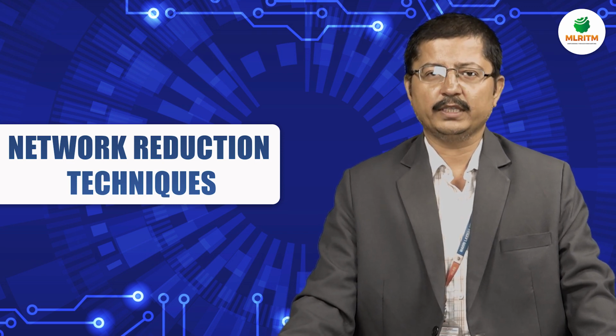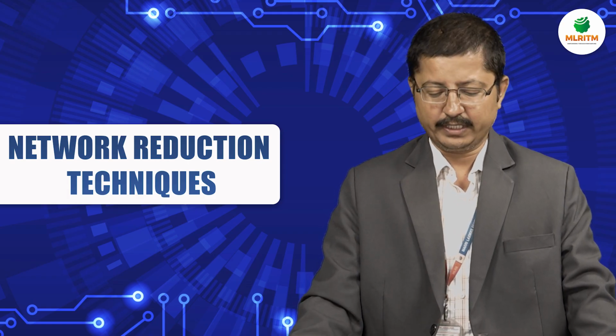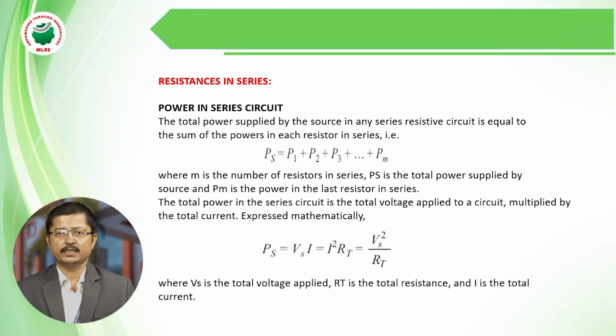To simplify the network, we have to use network reduction techniques. The techniques are series connection, parallel connection, series to parallel conversion, parallel to series conversion, voltage division and current division, star to delta and delta to star transformation, and voltage source to current source and current source to voltage source. Of course, the source conversions we already discussed in the last lecture. So today we will see the remaining techniques.